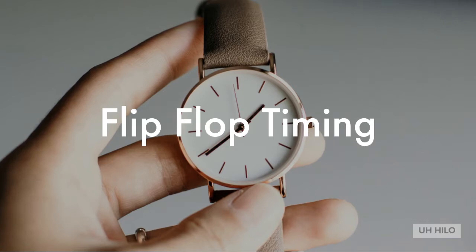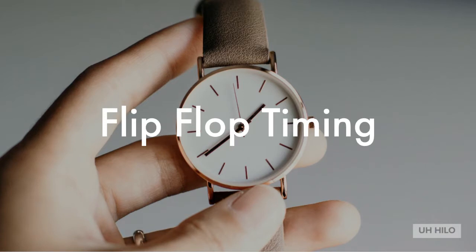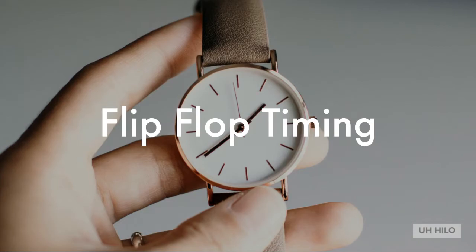Another item to consider is the hold time. This is a minimum time for which the S and R or the D inputs must not change after the application of a clock transition that causes the output to change. In addition, there is a minimum clock pulse width to ensure the sample has enough time to capture the input values correctly. Among these parameters, the ones that differ most between pulse-triggered and edge-triggered flip-flops is the setup time.